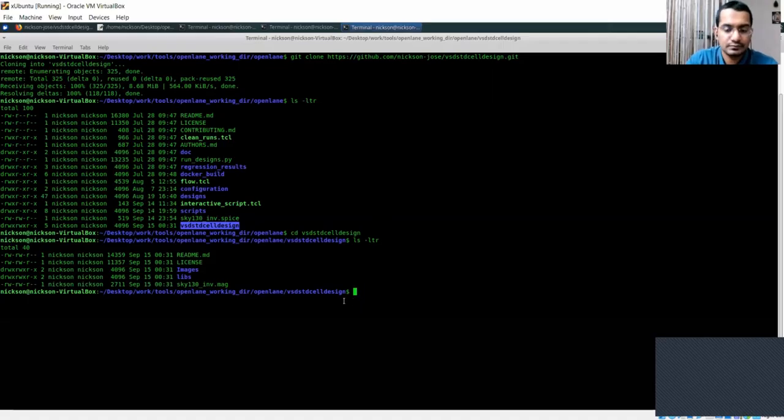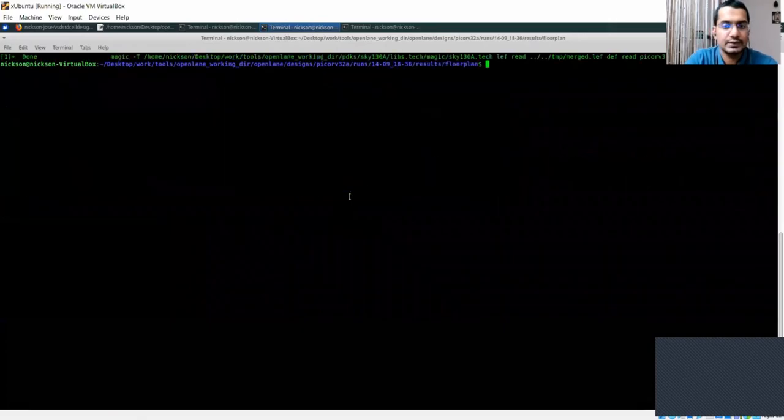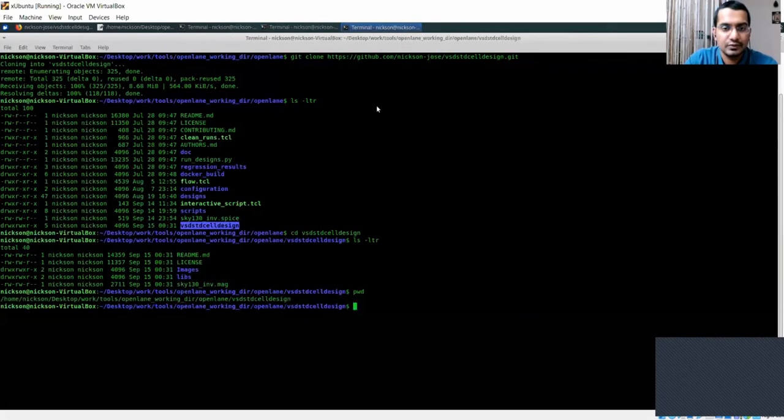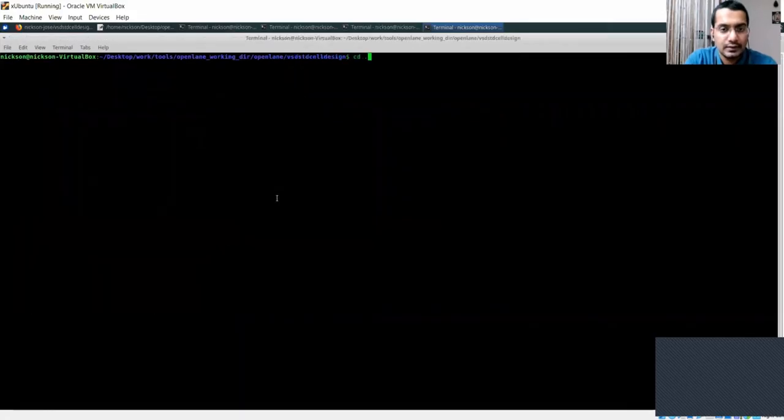Similarly, we'll be doing the same thing for all this set of combinations. I know it's tedious work, but we need to do it, and we'll plot a table specifying the value of your switching threshold and the value of your rise and fall delay, and eventually deduce a conclusion about the CMOS inverter robustness. So let's try to do all this in the next video.